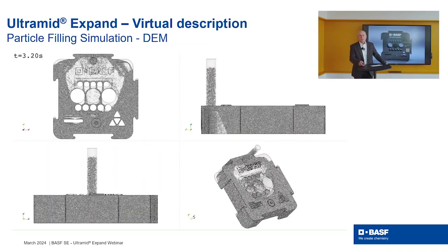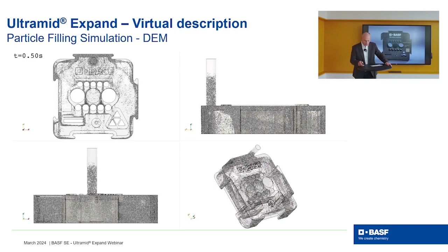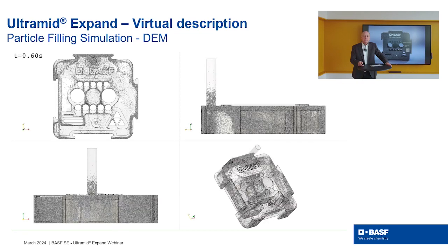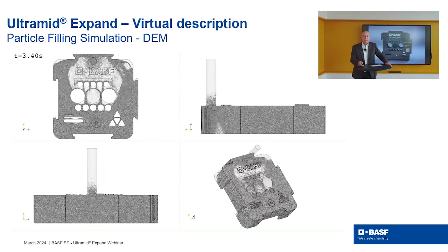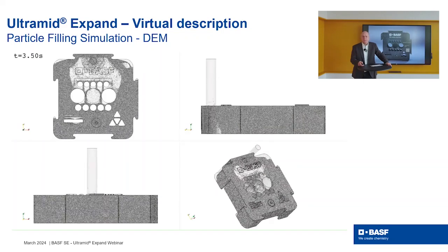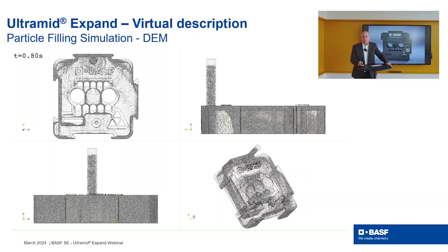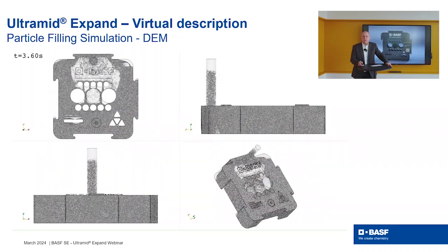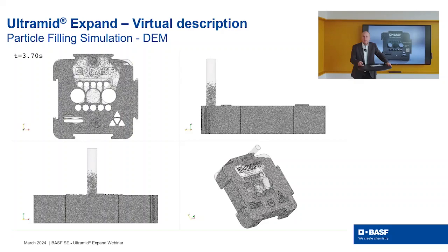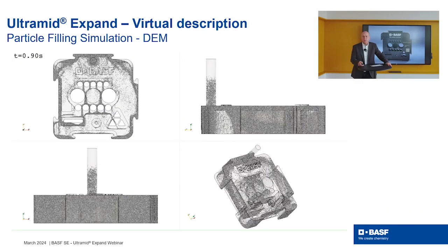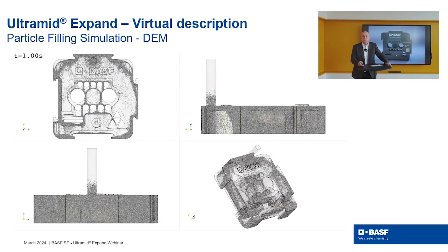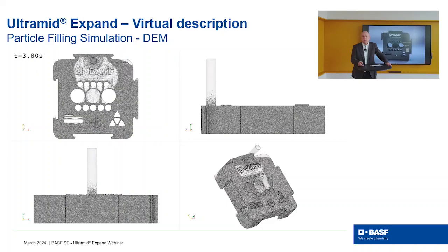This slide shows a completely different thing. Now it's all about simulation also, but we do not describe with the simulation how the foam material reacts when it's foamed. We here now simulate the foaming process and the filling process itself. This is a particle filling simulation with a discrete element method, and what you see here is the interaction of about 2 million parts on the computer. All have their own density, their mass, their velocity, and they can interact with each other. And we can now see and judge before we build the tool if we can fill the tool with the injector points that we have looked at.